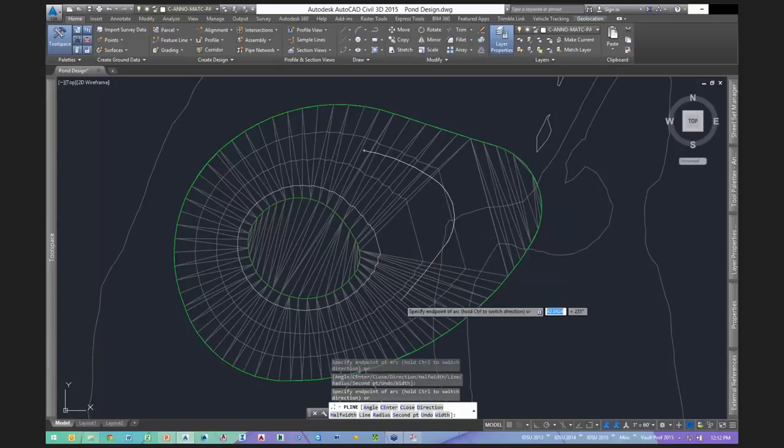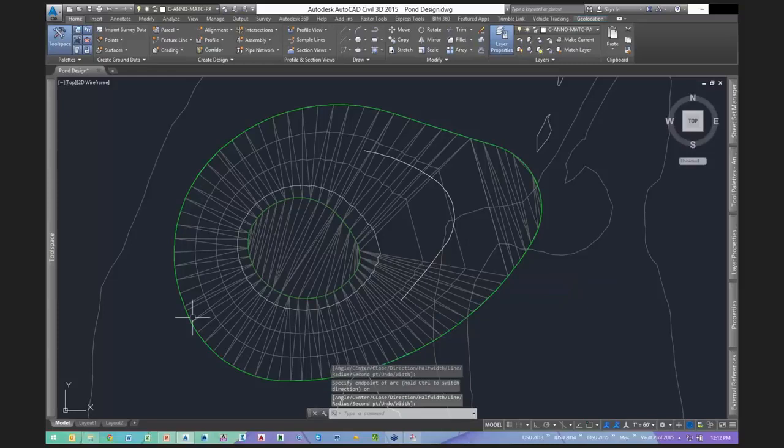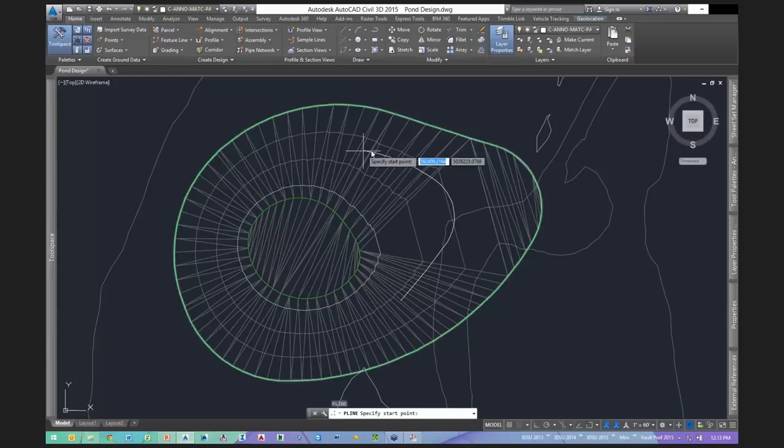And why am I doing this? Okay, it triangulates the way we want when things, again, are parallel and concentric. It doesn't do it so well when they are not. So we have to kind of split the difference and throw one more break line in here, possibly even a second one. Let me actually put 2 in here.